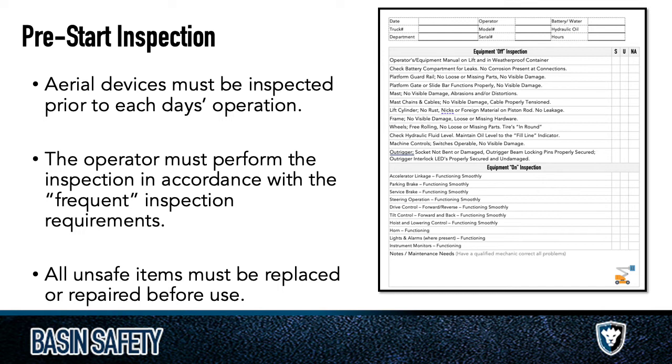Just my personal soapbox. Check how full it's supposed to be, and people just don't do it. You'd be surprised. I'll go to a forklift and it looks almost fine, but then you check it, and it's like 30 or 40 or sometimes 50% of required tire pressure. So just keep that in mind. Make sure you get that fixed and reported right away. Do it before every shift.